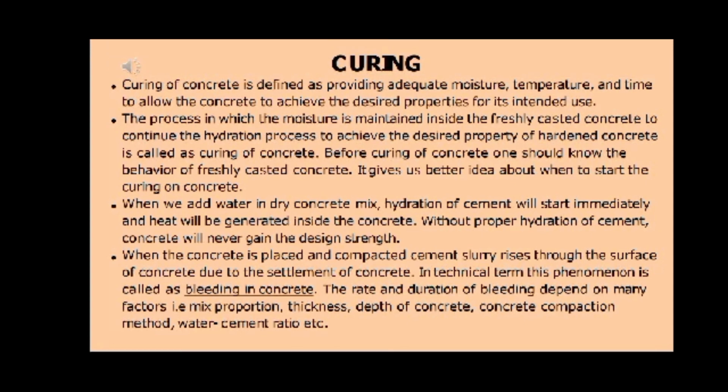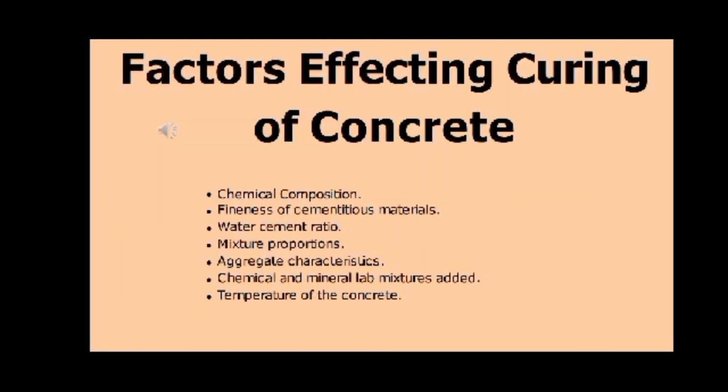When the concrete is placed and compacted, water rises through the surface of the concrete, a phenomenon called bleeding in concrete. The duration of bleeding depends on mix proportion, concrete compaction method, fineness of cementitious materials, water-cement ratio, mixed aggregate characteristics, and admixtures added.